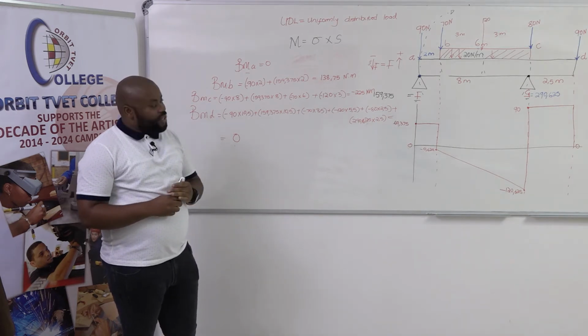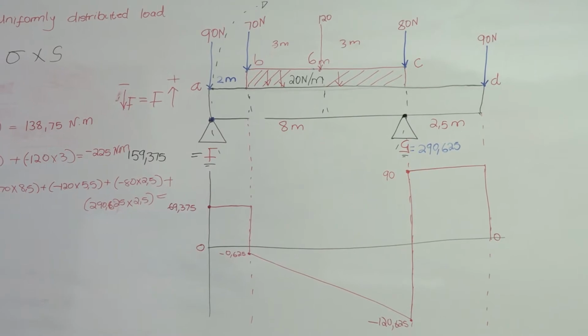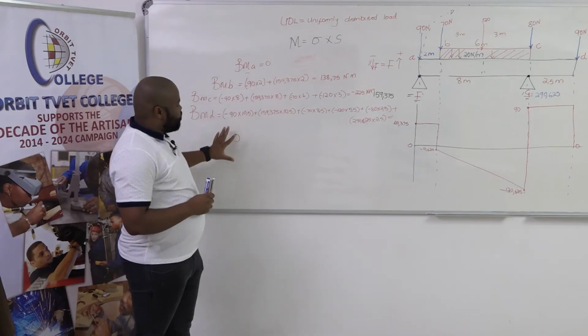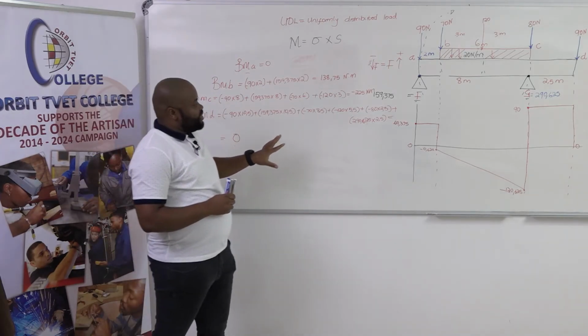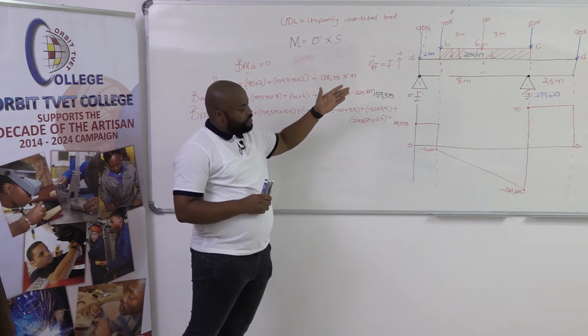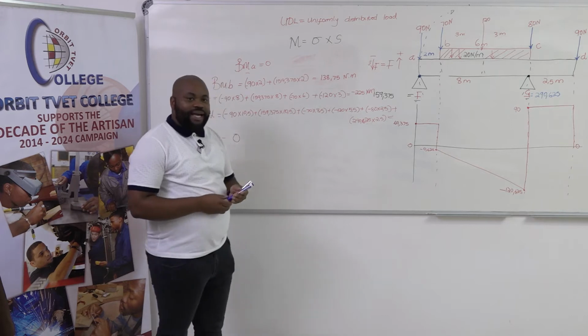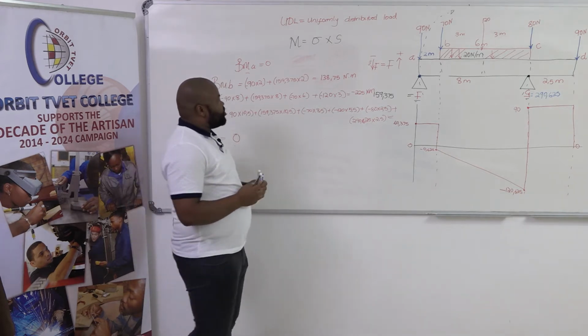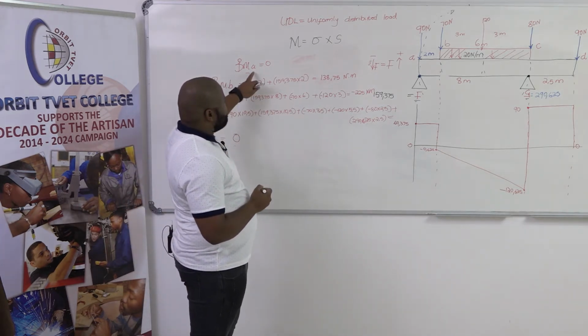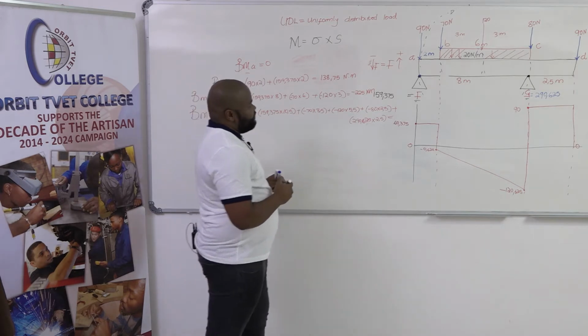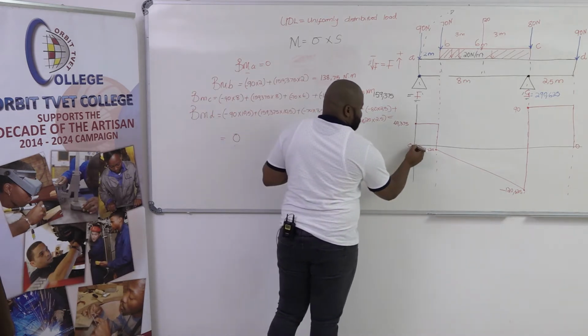on the beam. So from now, we're going to plot the values that we have calculated for the bending moments of this beam on the very same set of axes where we drew our shear force diagram. So our first point is bending moments at A, meaning that this is our starting point.